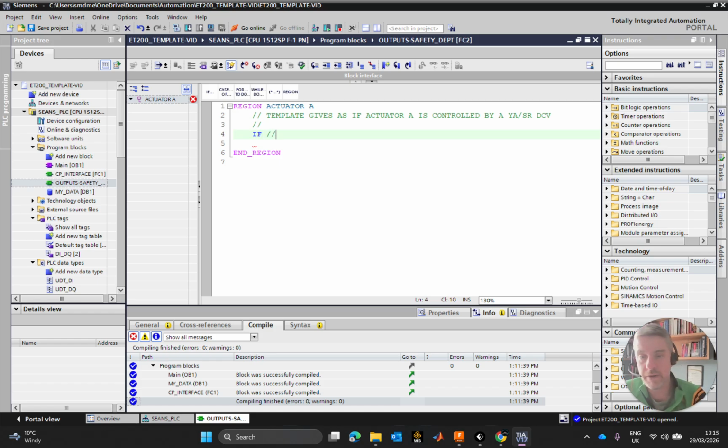All right, so I'm going to put in if. Now I'm going to put in a comment in here. Right, so this is going to be code for extending cylinder A. I change code to conditions. Conditions for extending cylinder A, for extending and keeping extended cylinder A. Just write that in. And maintaining cyl A extension. Right? I'm going to change that cylinder back to cyl.